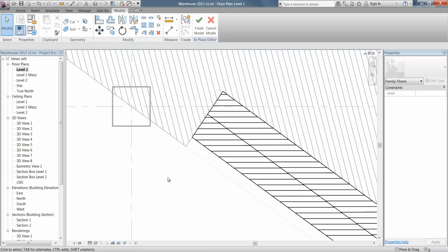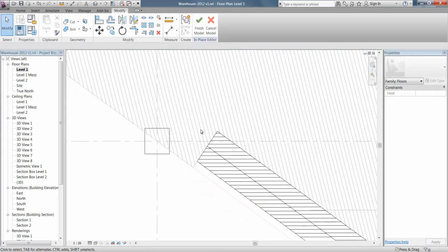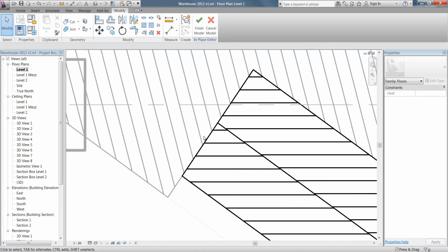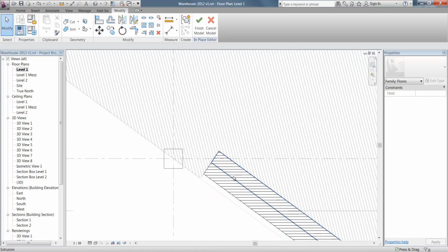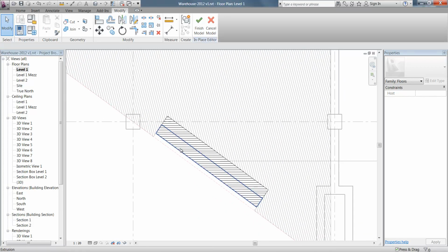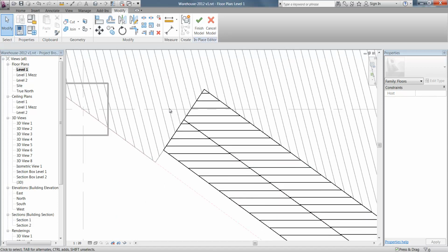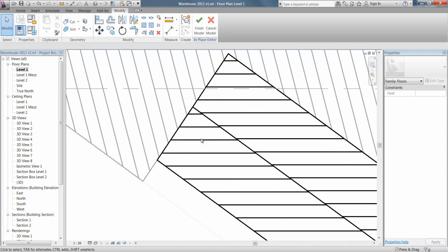Okay, so then there is one final thing. The flooring here is not at a very good angle. Okay, and so I'll rotate that around. It's really up to you the way you would go here. It's a tricky thing with floorboards on steps. It's probably something to avoid, but I'll just show you, just as an example, how to rotate the pattern around so it aligns with the elements, with the stairs.